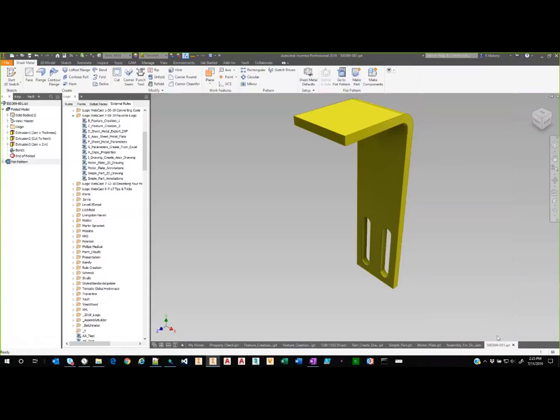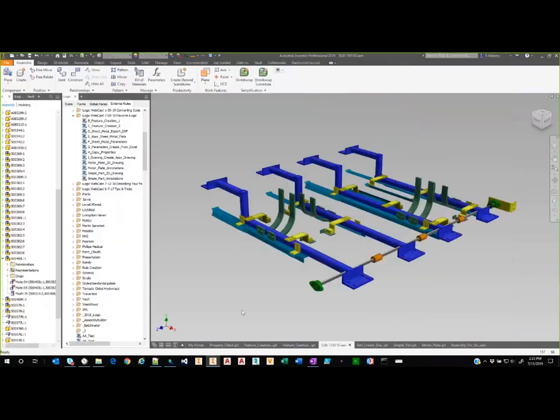So another thing we're going to do here from the top level is run through and again look at all sheet metal components. And if it is a sheet metal part, I want to take a look to see if there's existing parameters called flat pattern length and flat pattern width. Okay? If those exist, fine and dandy, I just move on. If they don't, I'm going to create them on the fly. And then I'm going to set those parameters to be exposed as an iProperty. Right? There's a checkbox over there in your parameters dialog box. Therefore, those iProperties can then be used, again, inside of my parts lists.